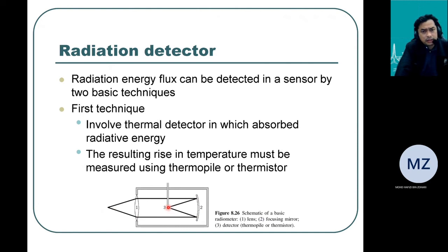That one point we measure the temperature using any kind of measurement device, for example thermistor, thermocouple, RTD. It's up to you. But it has a limitation of range. The limit is on the sensor that you put here at number 3. If you use the thermopile or thermocouple or thermistor or RTD, it depends on the ability of that temperature sensor to measure the temperature.